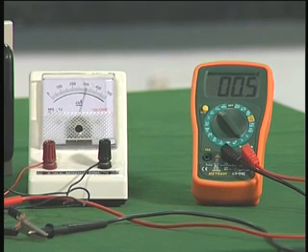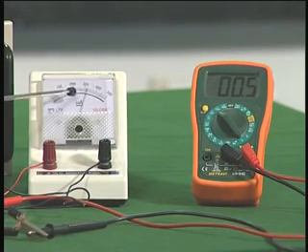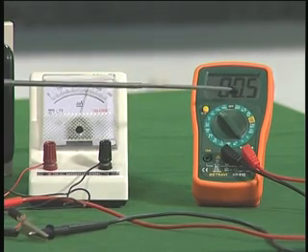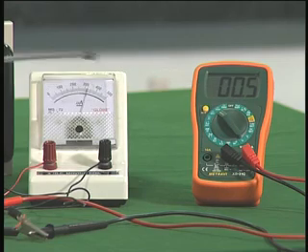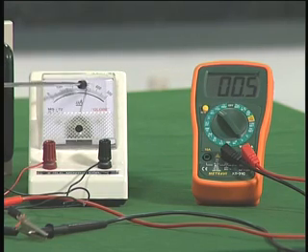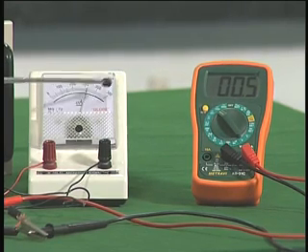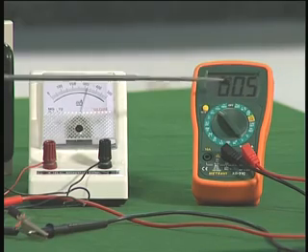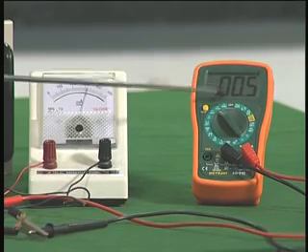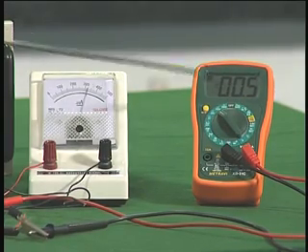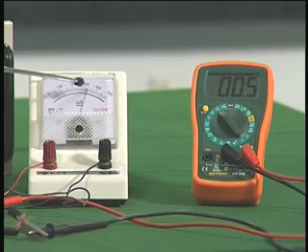Now you can see a large current of nearly 300 microamperes is flowing, and now the voltage has come to 0.5 volts. So when the large gate current triggers the SCR on, the 20 volts that we applied has now become 0.5, which clearly shows the SCR has come into conduction state. This is the gate current.